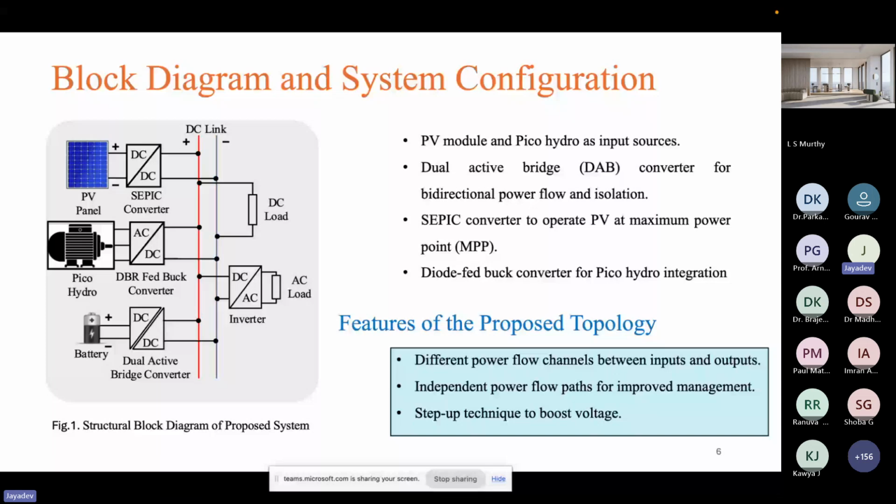But in this case, the DAB converter consists of a high frequency transformer, so on the secondary side we can use multiple terminals at multiple voltage levels. For this particular design, we can have multiple DC link voltages to integrate. Now you are designing for 220 volt. In future, if you are planning to increase to 400 volt, at that time also that single converter and the same transformer will help to integrate the battery.